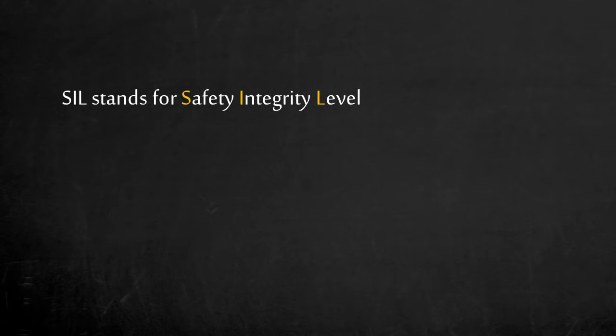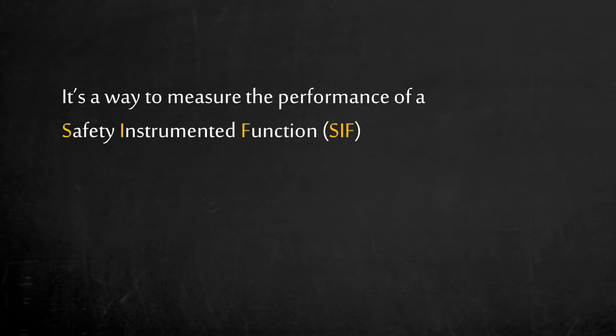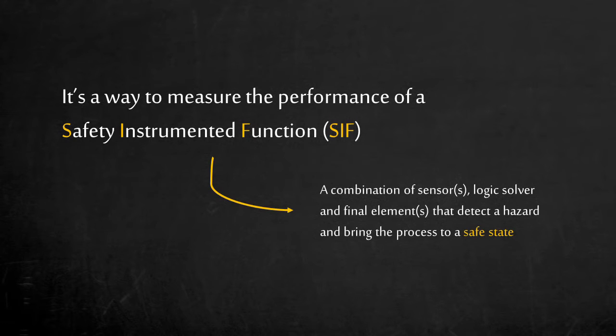Let's start off with what SIL stands for. The term is an acronym for Safety Integrity Level. SIL is used to define the reliability of a safety instrumented function as a way to measure performance. A safety instrumented function is a combination of sensors, logic solver, and final elements which detects hazards and brings the process to a safe state.